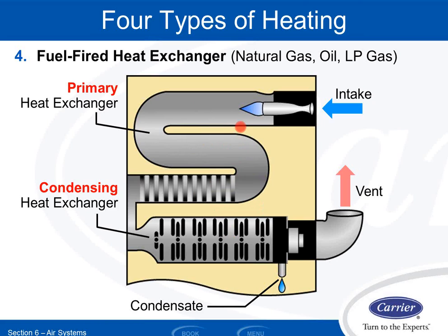So if I had a hot water coil with multiple rows, I would feed the hot water into the last row, and the return water would come back from the first row, the inlet row, if you will. That's the reason for that scenario. So hopefully that helps answer Robert's question.